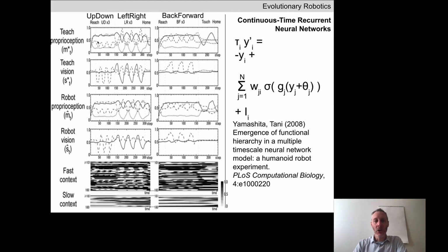Okay, so I don't have a video of that robot. It might be in the YouTube video we just saw, but better to look at a figure here. So we have time on the horizontal axis here. And what is being plotted here is a bunch of the proprioceptive sensors. We've talked a fair bit about touch sensors so far, infrared sensors or proximity sensors. Proprioceptive sensors report the angle of the joint in the robot.